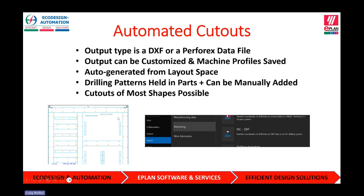as you need it, just by clicking and placing them straight onto the panel or onto other sides of the enclosure. And they're just exported through as you go through the file export machining, and then either this NC DXF or the laser Perforex or the BC Perforex. And cutouts of most shapes are totally possible. You can create polygons that you want to cut out. It's just down to a routing corner of about 3mm or 5mm, depending who you use to manufacture your cutouts.